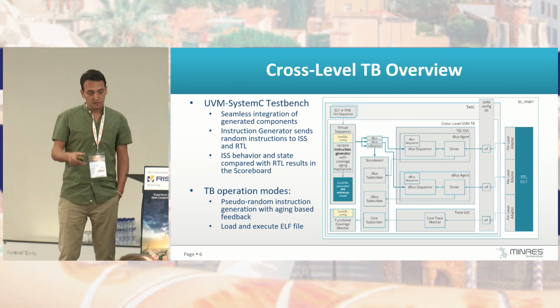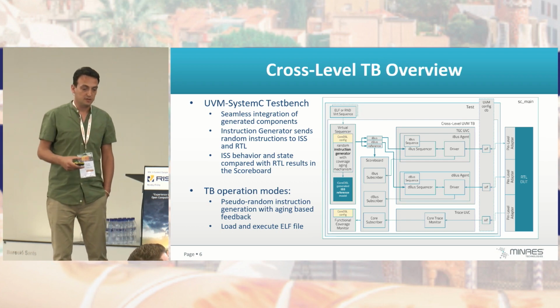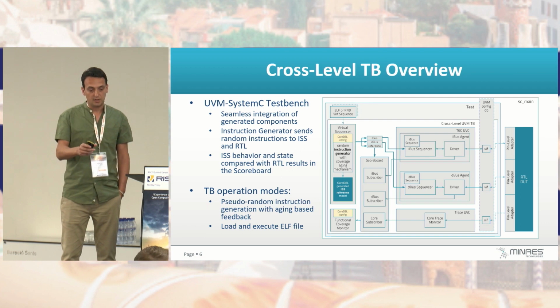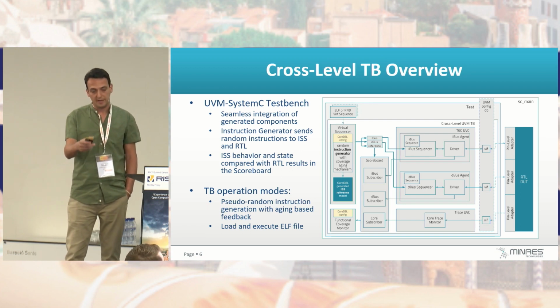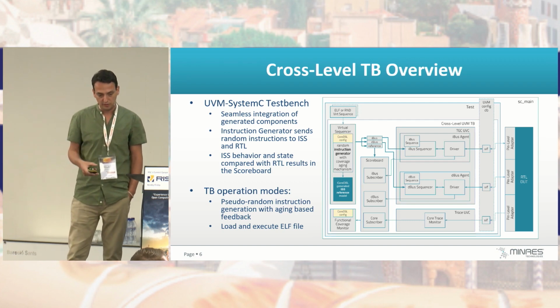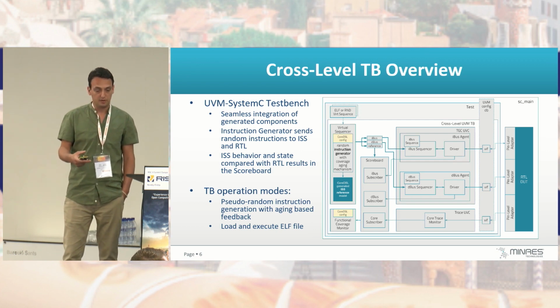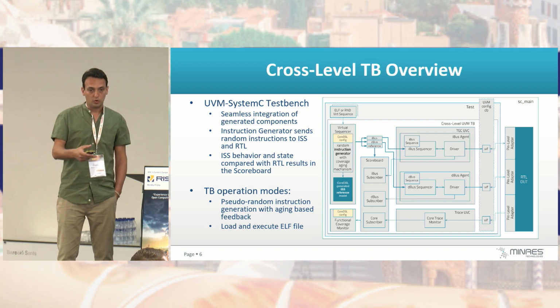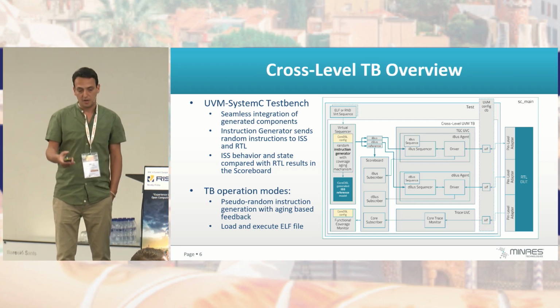So in a nutshell, the test bench uses ISS as a reference model, and instruction generator creates an instruction which will be fetched by both ISS and RTL DUT. The external behavior of the ISS and also its internal state will be observed and sent to the scoreboard, where it will be compared to the results from the RTL.